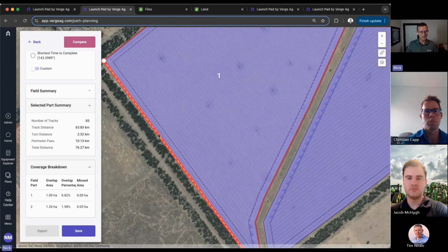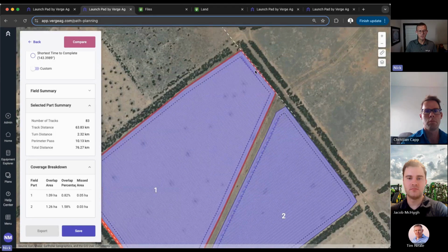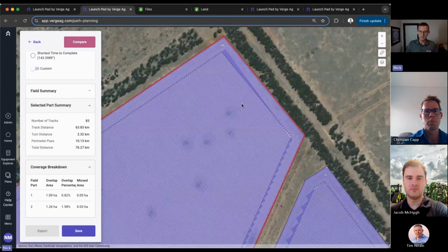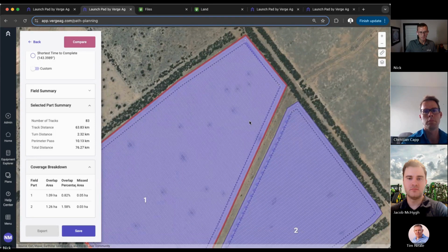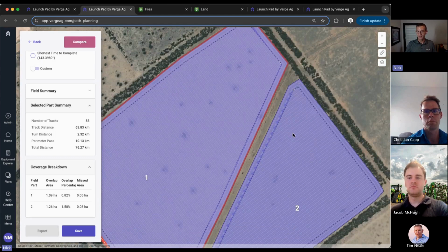So from the selected edge, we're going to always force every track over, about like the boundary track from John Deere. And there's going to be zero overlap on this edge. And we're going to push all of that overlap over to this edge, because even though users might think that their fields are rectangular and have parallel edges, they don't. So we help them understand where that overlap is going to go, etc.